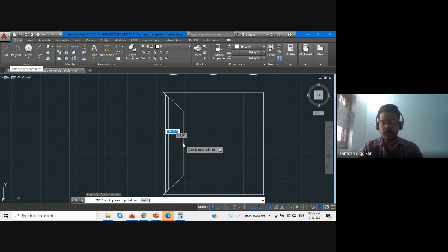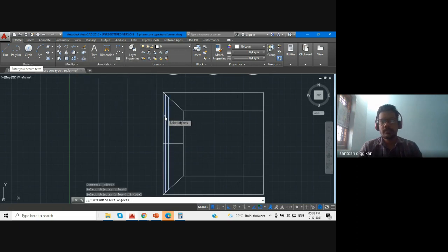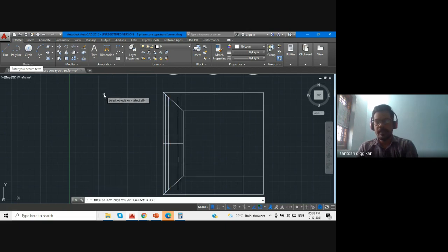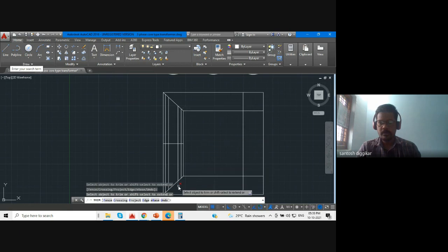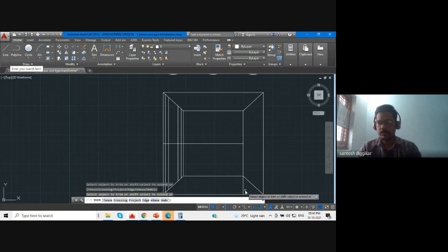Now we'll draw a center line. Now we'll make a mirror of these lines. Select these two lines, enter, click this, enter, and place here. Again go to trim, enter, delete the extra lines. Now again from this point draw a line over here. Again I will do a mirror. Before doing the mirror, I will first join these two corner points. Now trim, enter. Now we can trim these lines.